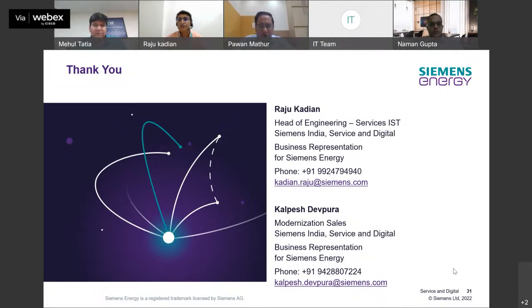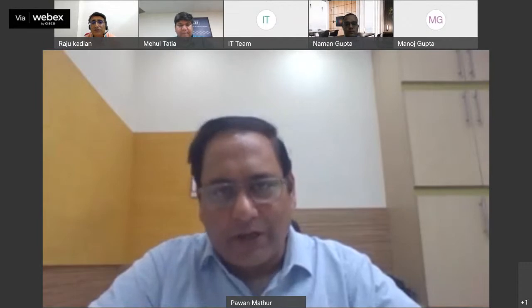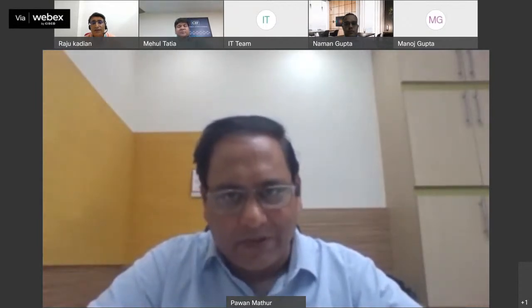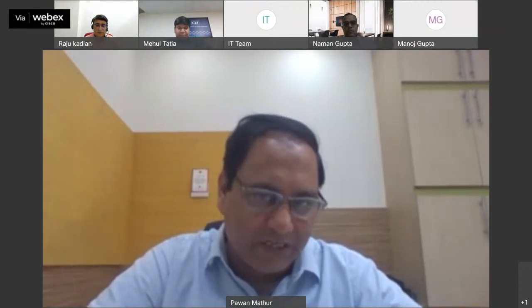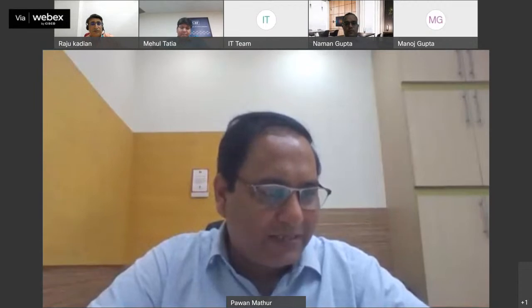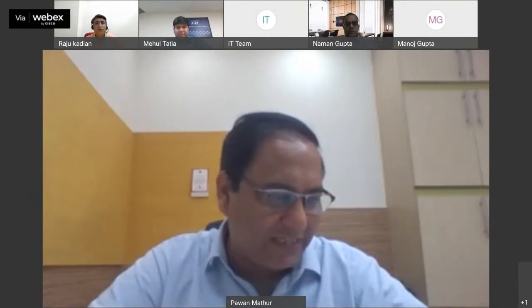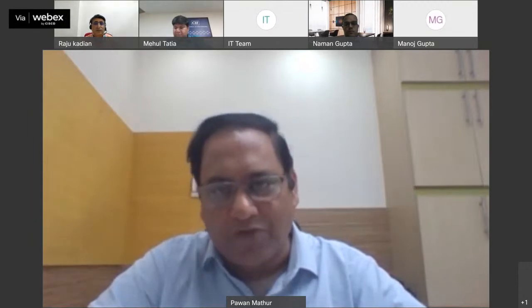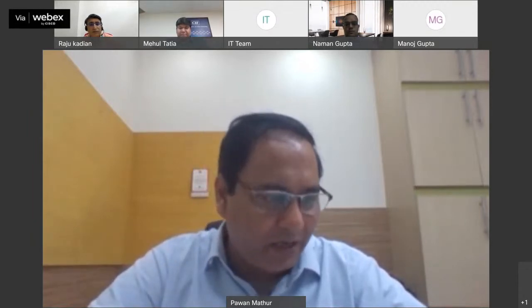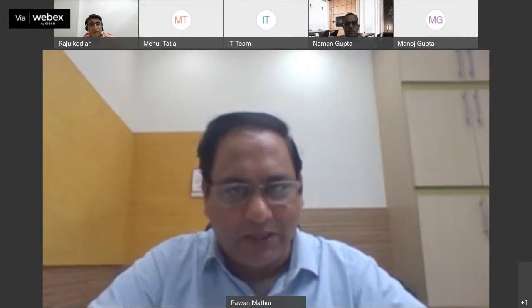I would just like to summarize your points. One of the things you emphasized is that 2 to 6% improvement scope can be there in Siemens turbines through various modifications, and you have shown case studies on blade selection and blade design, sealings, turbine casing and guide blade carrier, and valve designs. So this is the scope of improvement where efficiencies can be improved. You also suggested that part load management can be done using bypass techniques.